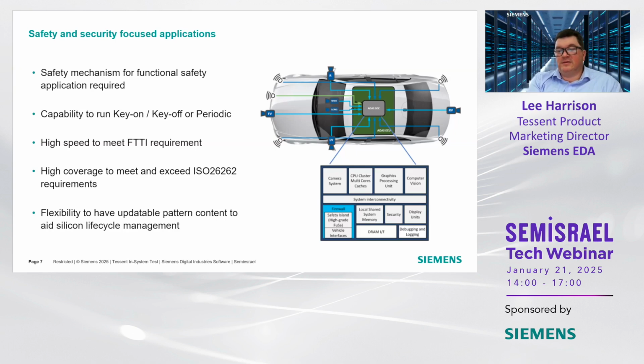In this case, the ISO 26262, which defines a time requirement, the fault tolerant time interval, which is when you need to be able to run these tests to identify any failures that occur. And again, the advantage here of being able to update the test pattern content to really improve the testability and to aid that silicon lifecycle management throughout the lifetime of the vehicle.